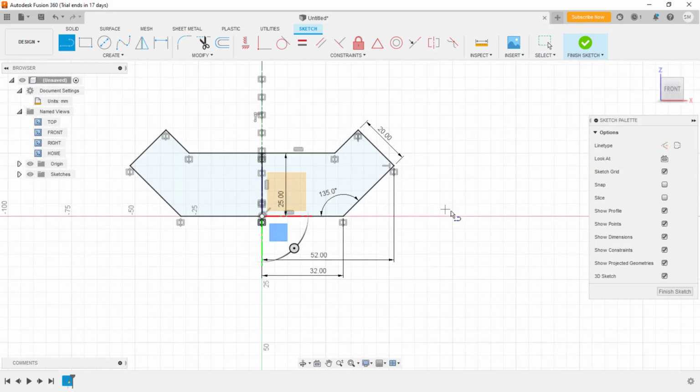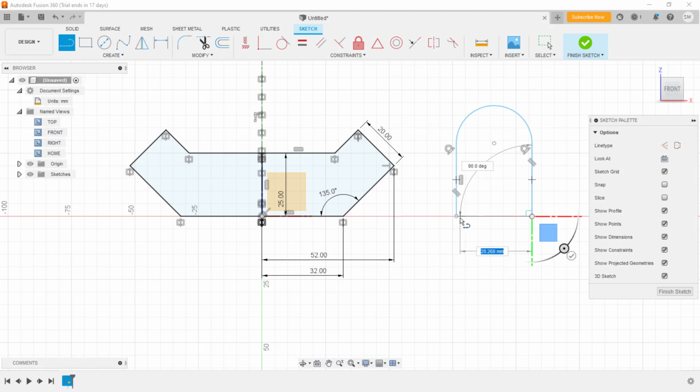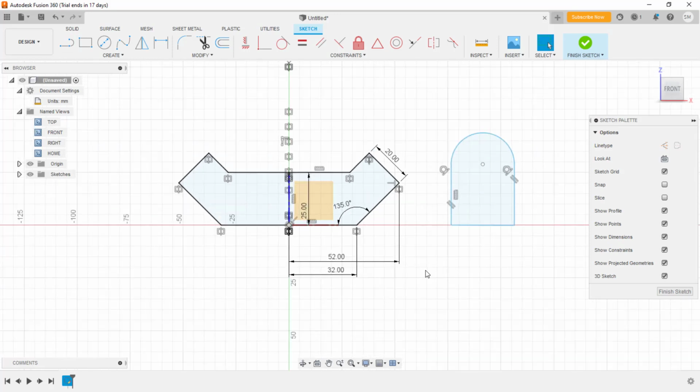And now, there is one more thing. To create the arc and automate these things, you can simply activate the line tool. Now simply hold the left click and drag it to create the arc. Okay, so once you're done with this, you can close it. So like this, you can create the arc and the profile in one shot, as we'll do in other softwares as well. So you can use it whenever it is required. Sometimes it won't help you to drag it.